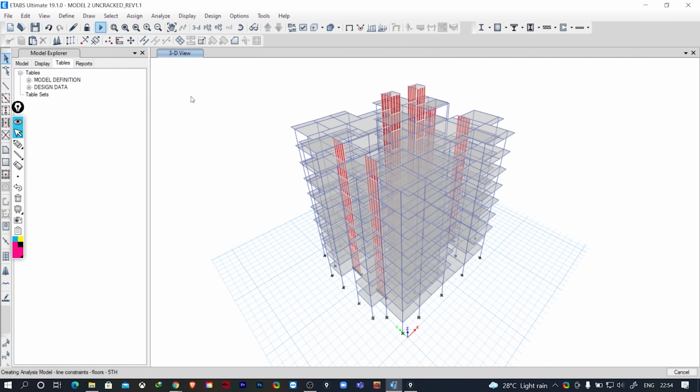If you are using a gaming laptop, it is a plus point for you. You can change this to gaming mode and use the multi-thread solver. Actually, we have different solvers in ETABS. So if you are using the multi-thread solver, it will be way faster than the process that we are getting initially.